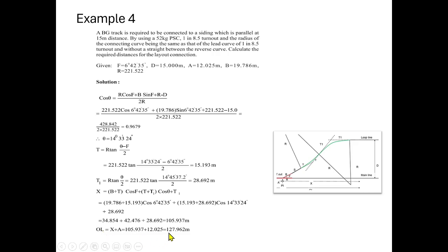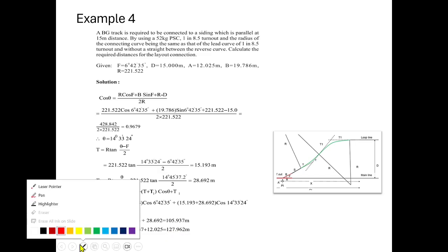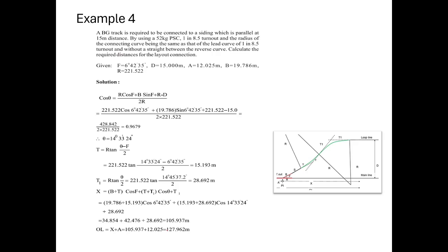Sorry, I think there is some mistake here. Our x distance is 105.937 plus A is 12.025, so it will come only 117.962. So please correct it, this is 117. Okay, this is 117. That will determine the tangent point.